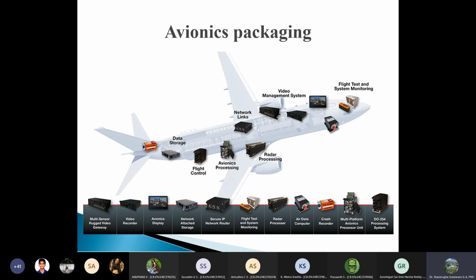So abilities to offer interconnects and mediation for signal travel from the various sensors to the processors is enabled using networks and dedicated controls for such information flow pathways, and the connectivity solutions that exist are mostly redundant, in a manner where if one pathway fails, there is still the possibility to get ahead with the actual data available from the various sensors. So that kind of a redundant pathway for interconnectivity that exists between the various sensors and the processors and the avionics display solutions is again one more aspect that is governed by a network link scheme implemented on board.